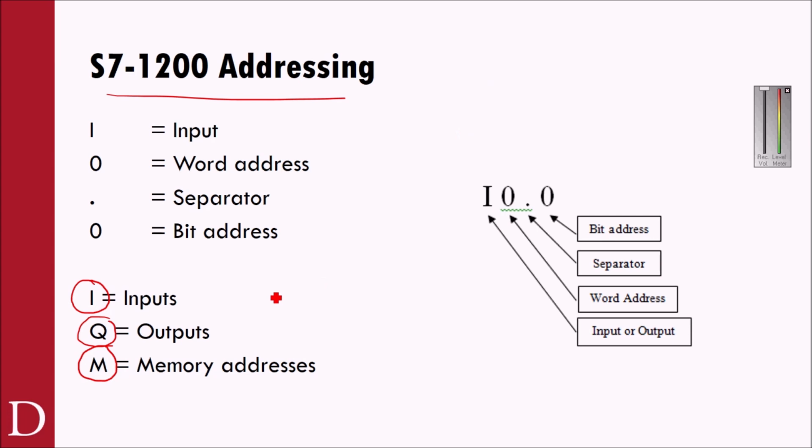However, be careful here. Part of the reason why they use a Q is because in Allen Bradley, it can be real difficult to determine the difference between a 0 and an O. So they actually use a Q for the output. If you look at like a Mitsubishi PLC or some other PLCs, they'll use X's and Y's. Everybody's got different syntax, but overall it's the same stuff.